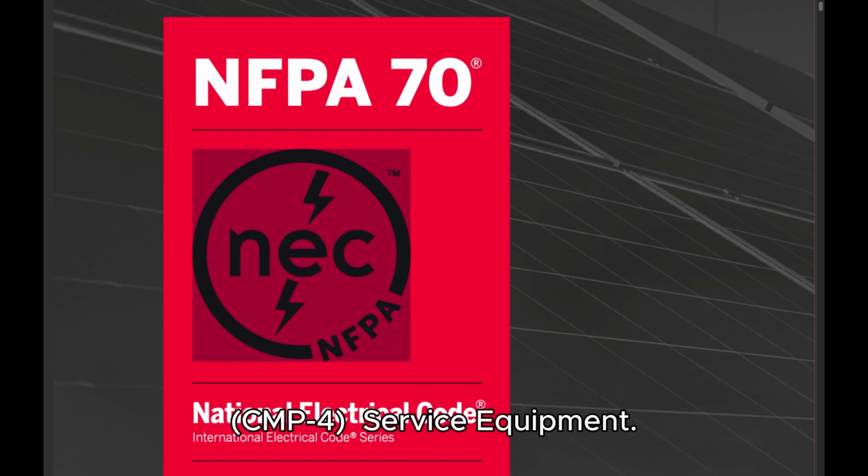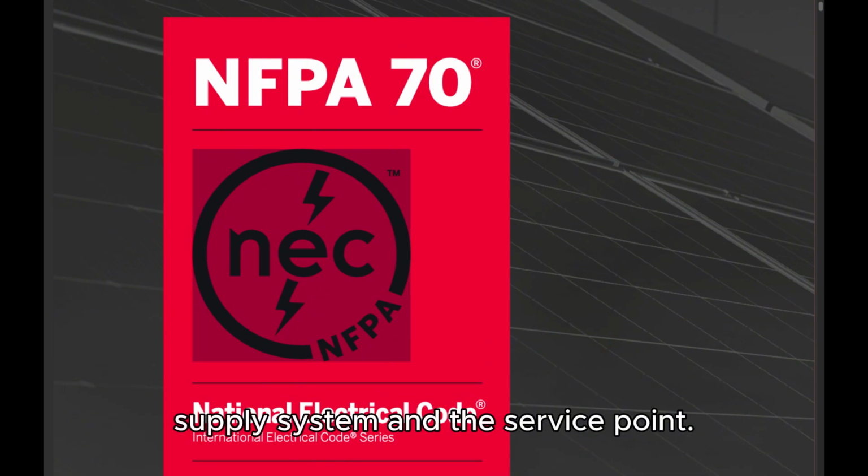CMP4 service equipment. The necessary equipment, usually consisting of a circuit breaker(s) or switch(es) and fuse(s) and their accessories, connected to the load end of service conductors to a building or other structure, or an otherwise designated area, and intended to constitute the main control and cutoff of the supply. CMP4 service lateral. The underground conductors between the utility electric supply system and the service point.